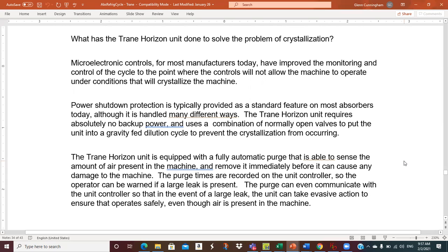So you might have a situation where you have to make sure that if power goes off, we have to close this valve. So you just put a normally closed valve in. Lose power in the control system, the valves are usually spring loaded or something, so they have their own energy source right there, and bingo, the valve slams shut. Or in this case, the valve slams open. So I want to make sure that you get that terminology, normally open, normally closed valves.